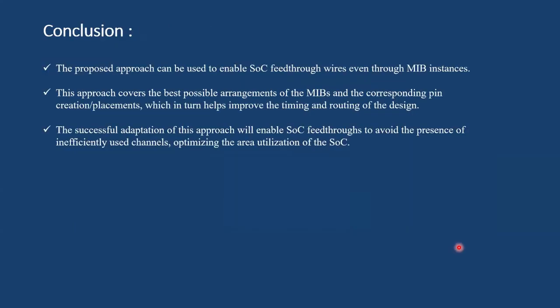So the conclusion is the proposed approach can be used to enable SoC feedthroughs, even through MIB instances. This approach covers the best possible arrangements of MIBs and the corresponding pin creation and placement, which in turn helps improve the timing and routing of the design. The successful adoption of this approach will enable SoC feedthroughs to avoid the presence of inefficiently used channels, optimizing the area utilization of the SoC.